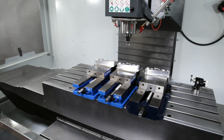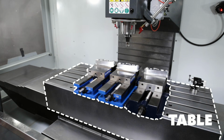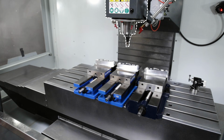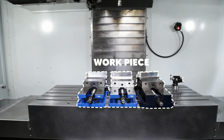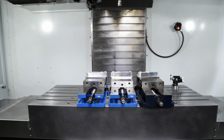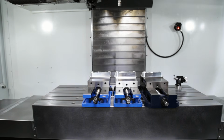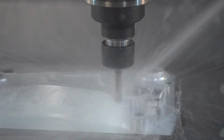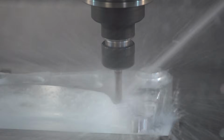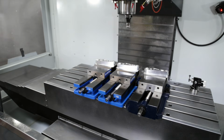As we saw in the first chapter, a typical CNC milling machine has a table and a spindle. The table supports the workpiece we'll be machining, and this table can move side to side and front to back. The spindle is what spins the cutting tool that does the actual machining on the workpiece. The spindle moves up and down relative to the table.